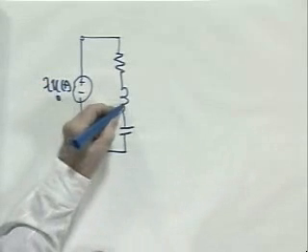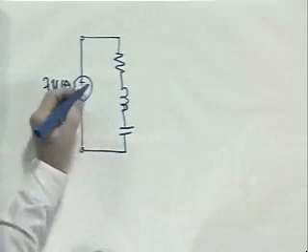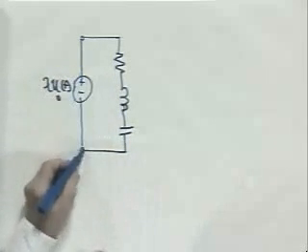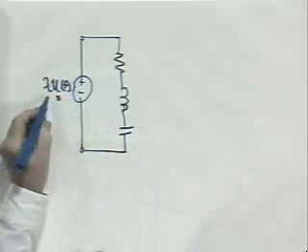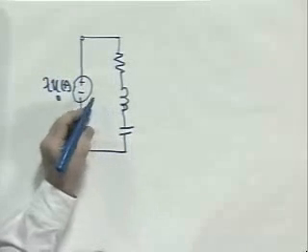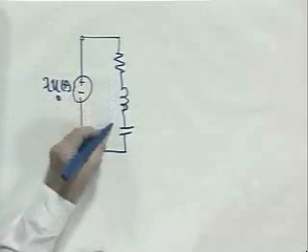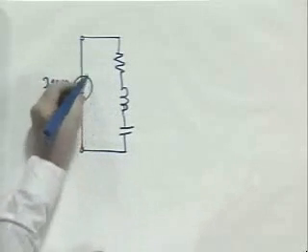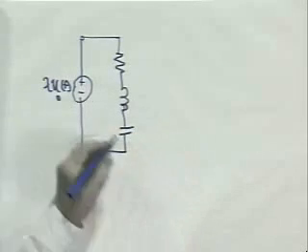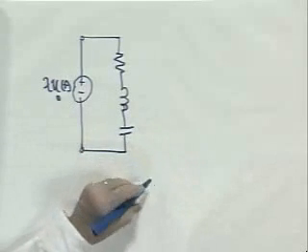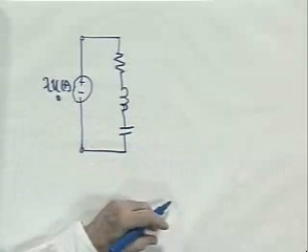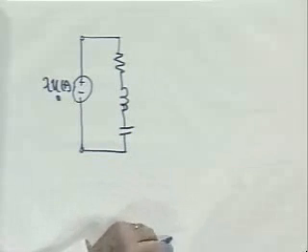That dumps some energy into the inductor, and the circuit starts out with a circulating current. Notice that after the impulse is gone, this source can be replaced by a short circuit. It has a value only at t equals 0. That dumps some energy into the inductor. So the circuit starts out with a specific circulating current in this loop with no voltage across the capacitor. You find a current which varies as the initial current times cosine omega t, and a voltage across the capacitor which varies like sine omega naught t, if it's lightly damped.